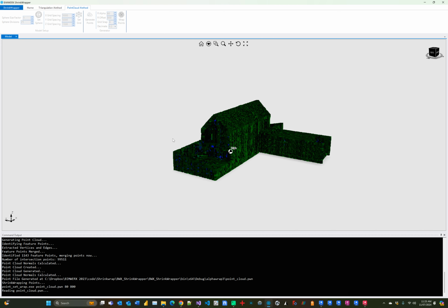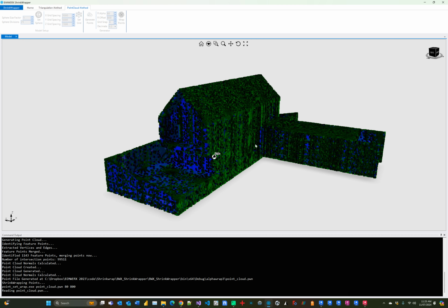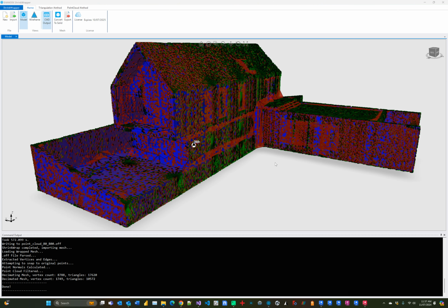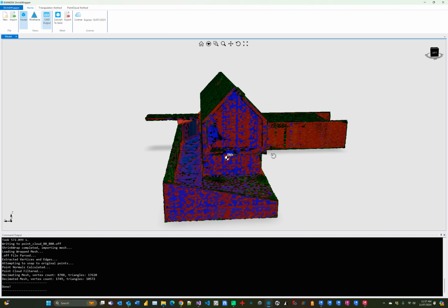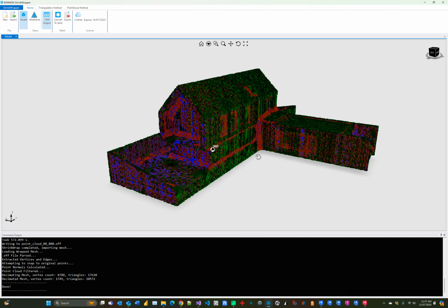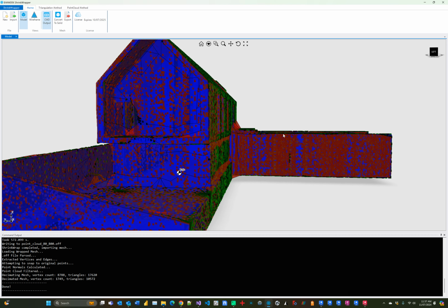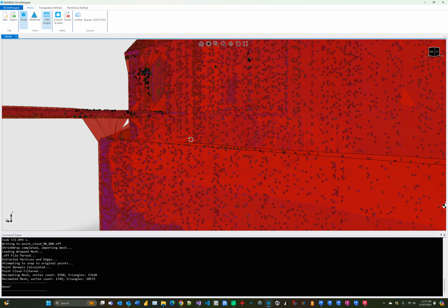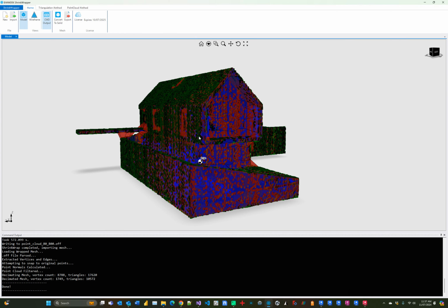Again, we set the relative alpha and the relative offset and grid snapping and the decimation values. And we're going to run the wrap points command on this one. And when it's finished, it's going to create that mesh again. And once we've done that, we can investigate it a little bit. Of course, the resolution on this one is not super high, like I mentioned before. We can set it much finer. It will take longer. This one took about, I guess, 5 minutes to run.